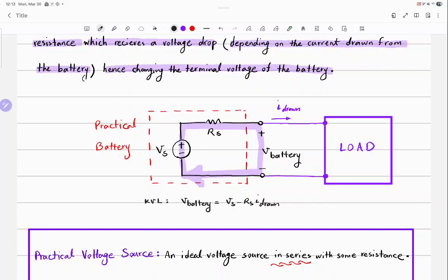Keyword, me and Braylon. Do you remember the example I gave you previous week? I can write a KVL between our heads in this room. Are we connected? I guess not. So for KVL, do you need some physical elements or wires or whatever? No. You can go from any point to any point and write a KVL, as long as it's a closed loop. It doesn't even have to be a mesh. It can be a big loop.